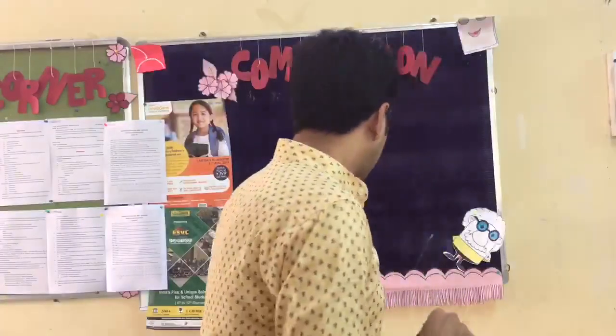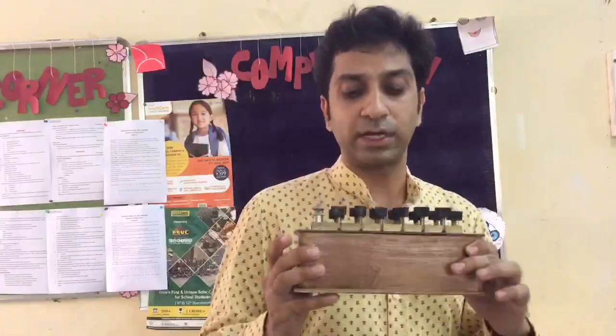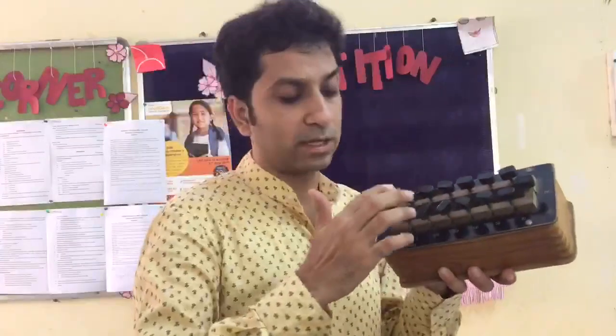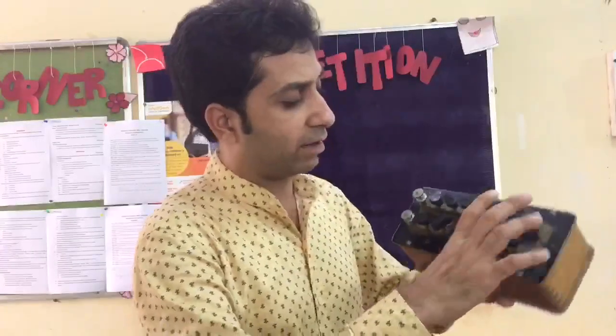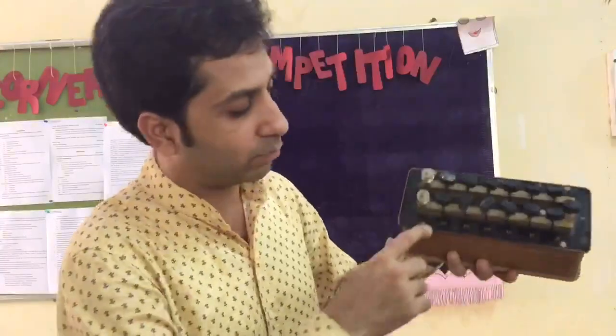And one more thing I want to say, always remember, an ammeter is connected in series while a voltmeter is connected in parallel. Then one more thing I will show you, which you should also be aware of. It's called a resistance box. See, there are a number of keys on this, and the values are written: 1, 2, 3, 5, 10, and so on up to 500.